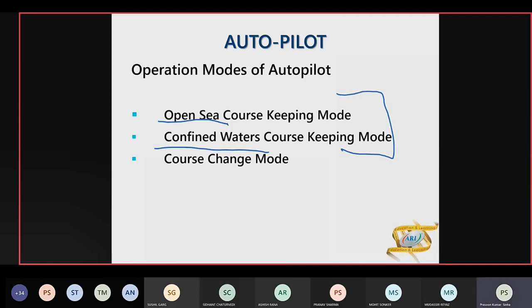So in bad weather, the behavior of the ship changes. So we have gradations of bad weather, very bad weather, or moderate, or good and very good weather. For those kinds of situations, we have this weather switch, with which I can select preset values of all the controls. I don't have to adjust all controls one by one, but just by changing one mode, all settings are done accordingly.